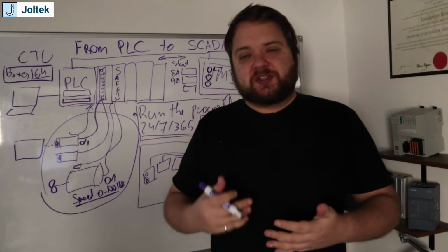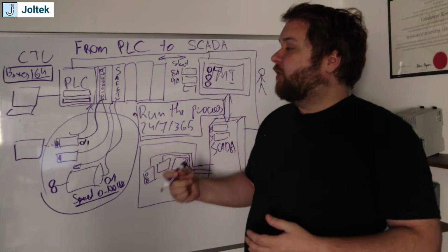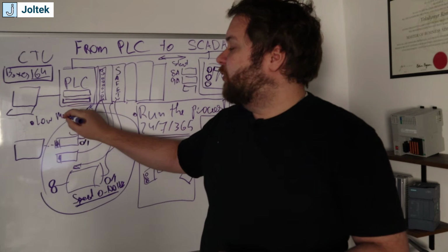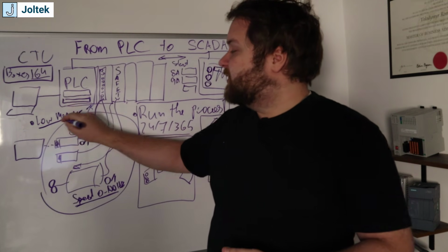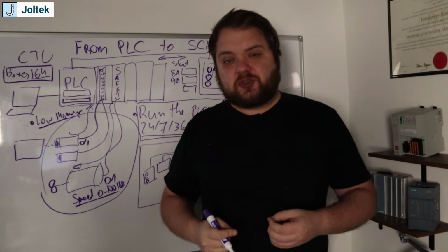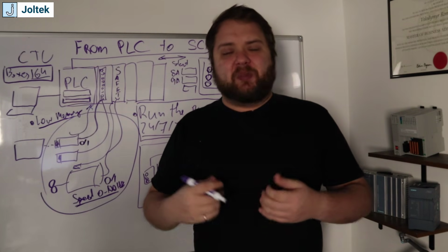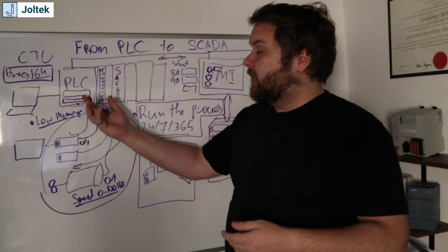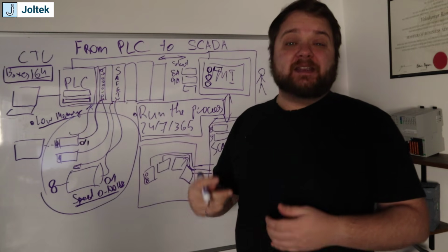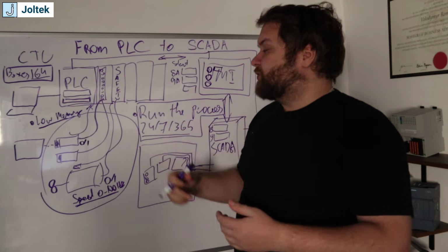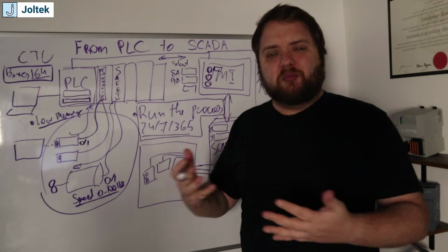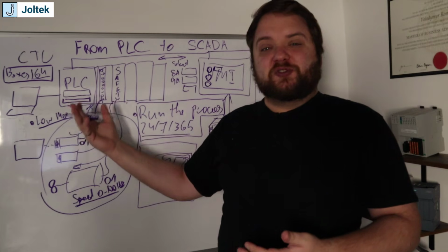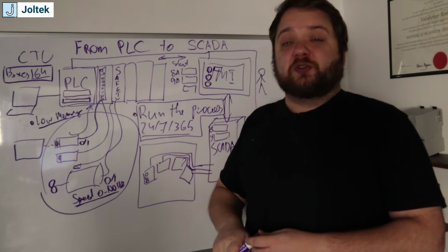Do you want that information? That's a whole separate discussion, but ultimately here, your PLC is low on memory, which basically means that any data structures, any arrays, any batch applications, for example, are going to be very difficult to run on the PLC in a scalable fashion. Of course, there are going to be exceptions to the rule. Like I said, you can buffer some of your data for a certain period of time, but you probably don't want to use your PLC as your database.